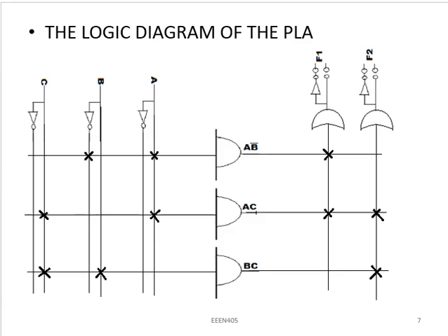Now, after doing this, the next and last step of the solution is to draw the logic diagram. And for us to draw it simply, we use the single line diagram we have been discussing previously in other lectures. So I say this is A, this is B, and this is C. I draw a horizontal line, a vertical line going down for A, and I pass it through an inverter, another line going down to give me A prime.